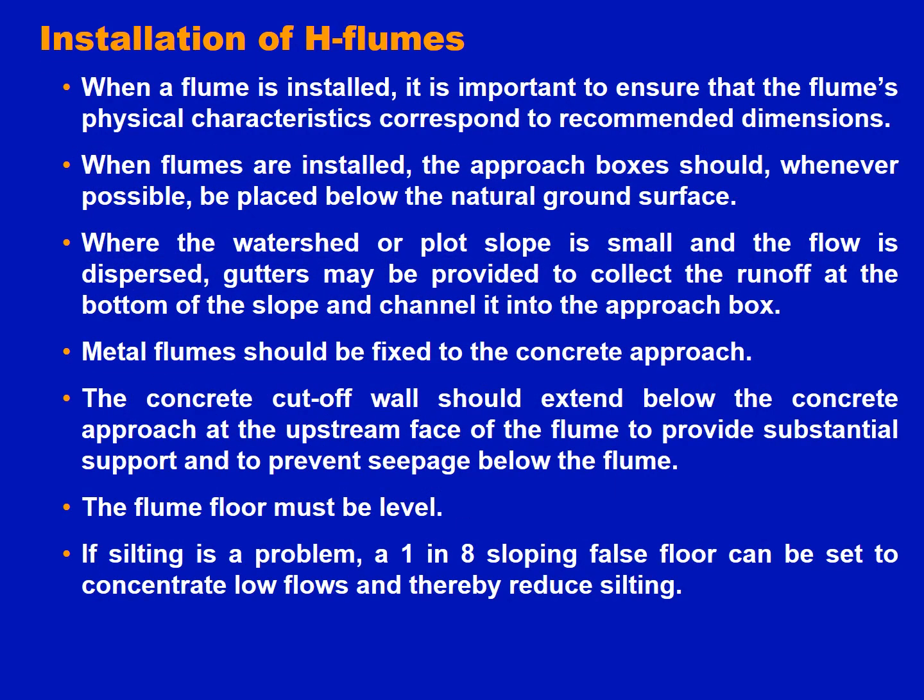Now some points about installation of H flumes. It is very easy. When flumes are installed, the approach boxes should, whenever possible, be placed below the natural ground surface. Where the watershed slope is small and the flow is dispersed, gutters may be provided.